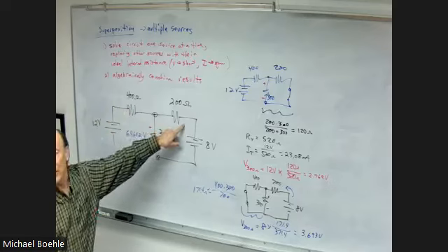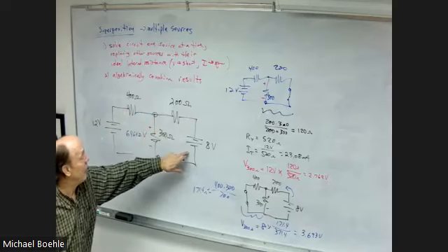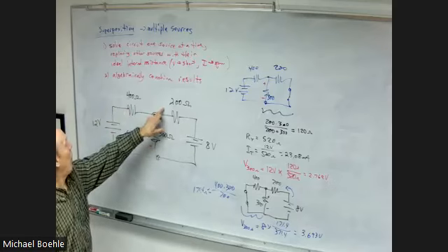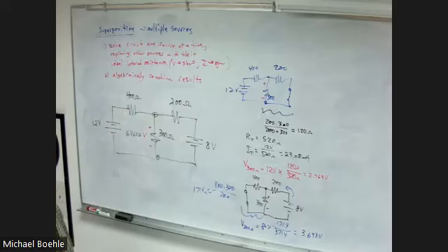What's the voltage here? Well, now I do this loop, it's 8 minus that. That's 1.44 volts. Now that I have the voltages, I can use resistance to calculate the current. I can basically solve all the rest of the circuit from that one piece of information. Make sense? All right. Now, how are we doing here? Okay, so that's superposition.